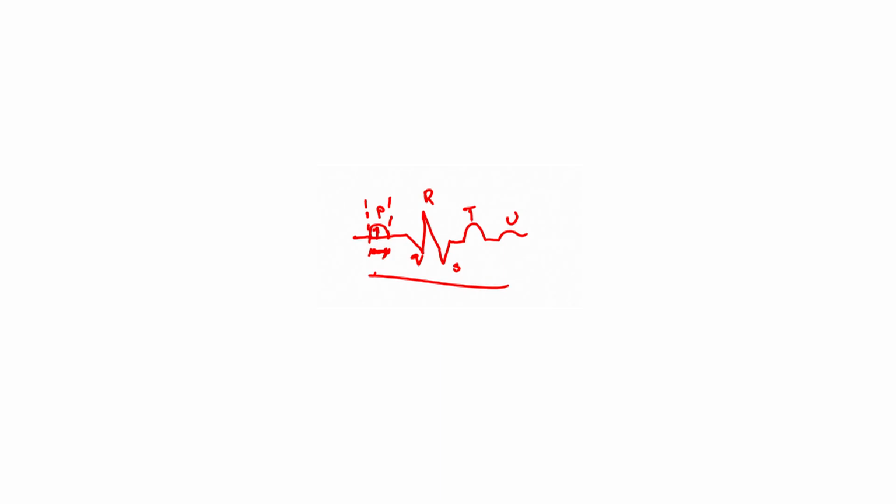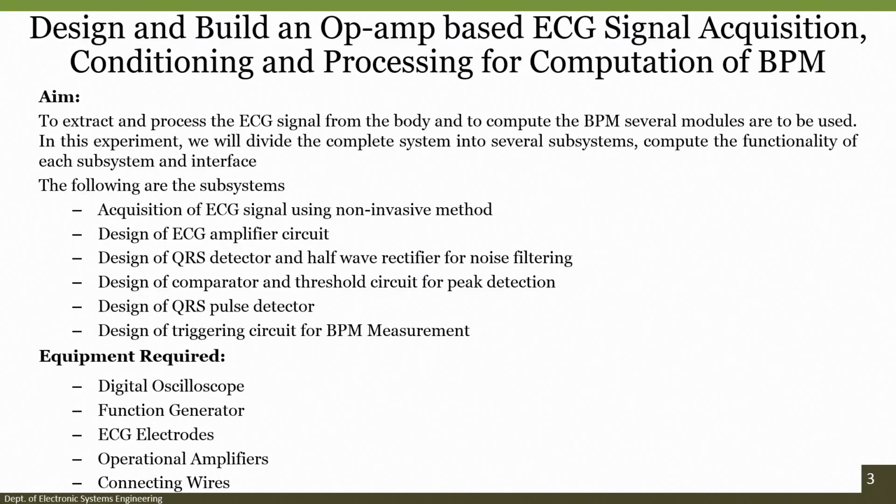Right. So, in order to understand, we should know how we acquire an ECG signal. In fact, the amplitude of an ECG signal will be either in microvolts or in millivolts, and the signal we get is not a simple output voltage. We always have to take a difference between two sources.